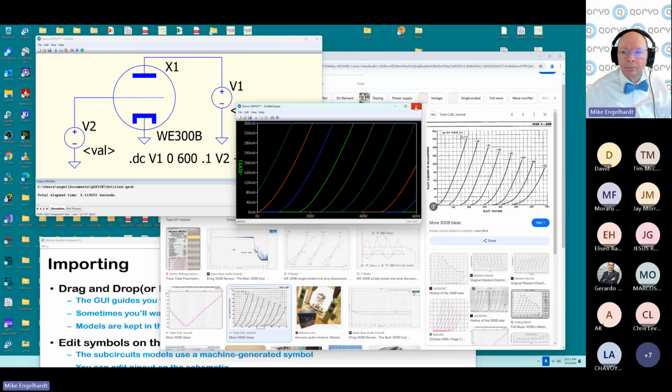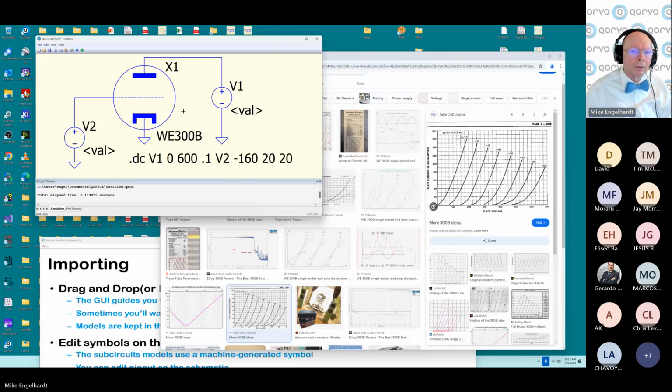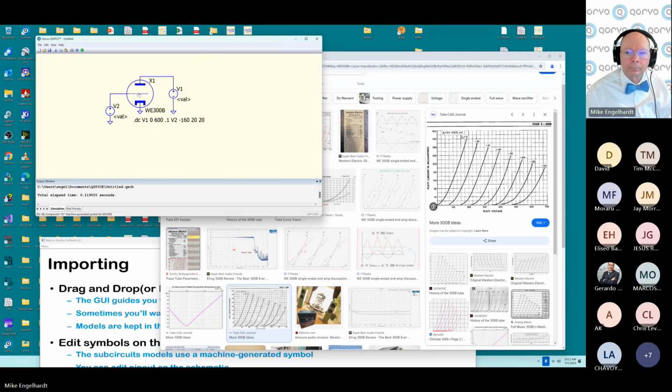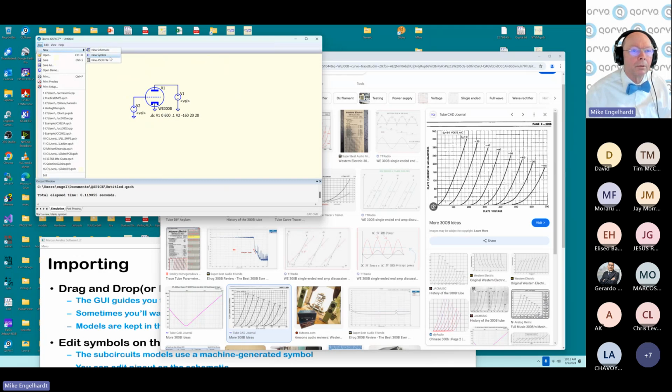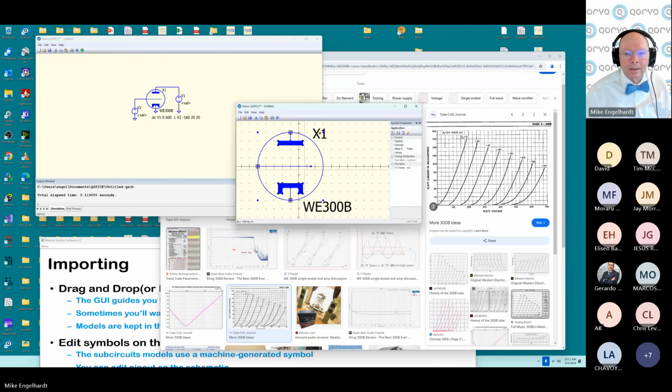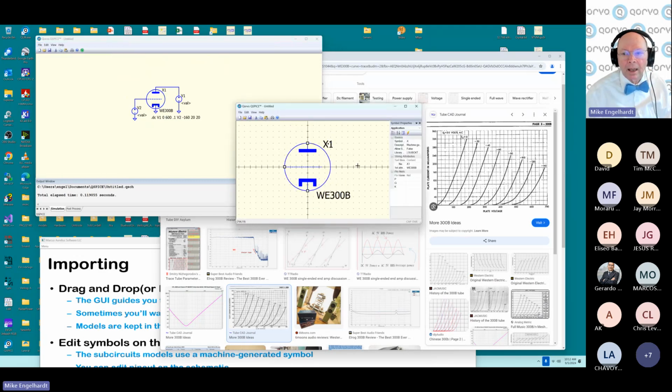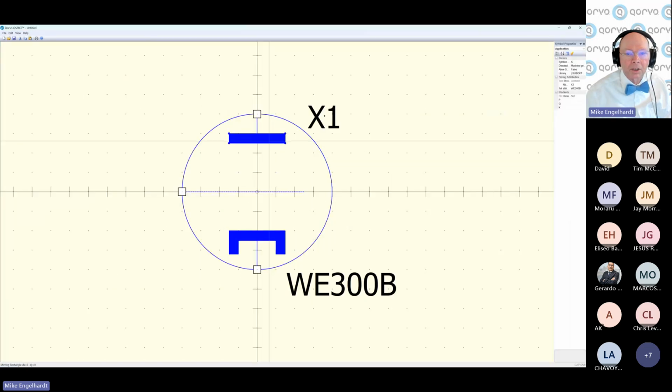Well, that's how you. Oh, I know. Control C. Let's do that in the symbol editor. View, new symbol. Let's put this here. And now let's talk about grid size. If I move here, the grid seems fairly primitive. Hold down Shift, it's finer. Shift, Control, and Alt also.